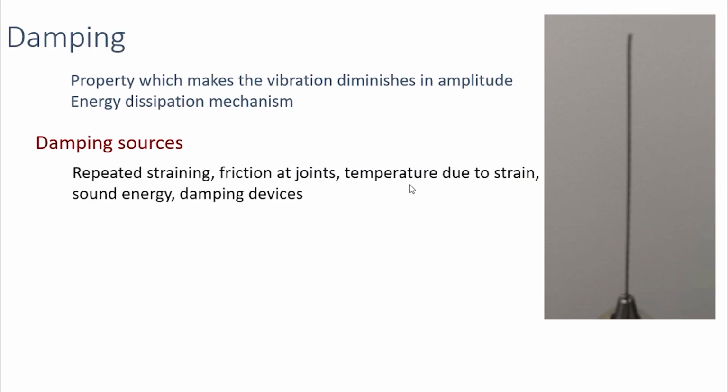So, when we stress a structure, because of the strain, sometimes some temperature is developed. So, that needs energy. So, that is also a cause of energy dissipation. In some systems, when vibrating, sound energy is produced. So, that is a cause of damping.